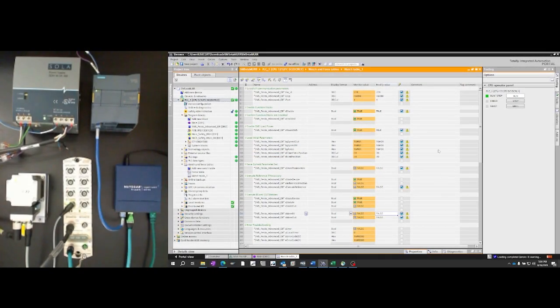Well, there you have it. Now we've confirmed we have both the process and parameter channels enabled. We confirmed that we had the process channel enabled by getting the X state in, X state device, and X state out bits true or false depending on the current situation. We also tested that by utilizing the X move in and X move out bits, which are processed cyclically. We checked the parameter channel by changing our force, speed in, speed out, and our positions for in position and start press position to 30 from 0. Thank you very much for your time.